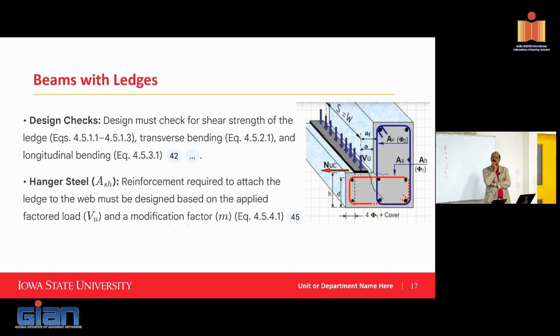When I have a corbel, the top of the corbel is always undulated, with micro undulation. This bearing pad will feel everything. So it is two ways: structurally and waterproofing, and how we made it easier for our erectors. Yeah, it's required there. So one is to make sure that there's full contact between the two. So they definitely rely on bearing pads as a specification.